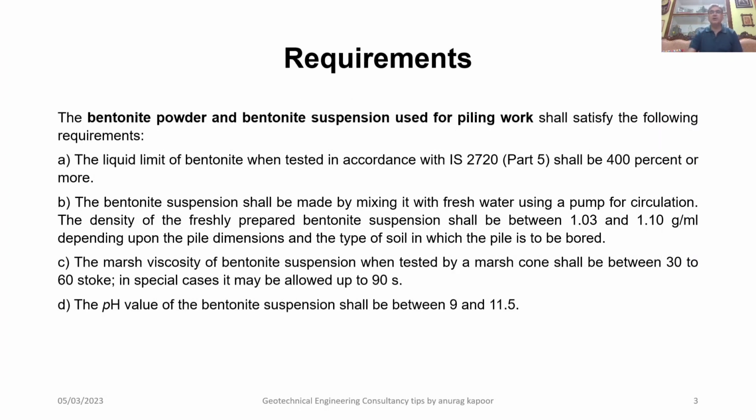Now, coming on to my last slide. The requirements of bentonite. The bentonite powder and bentonite suspension used for piling work shall satisfy the following requirements as per the two respective Indian standard codes, which I had referred to in my first slide. The liquid limit of the bentonite when tested in accordance with IS 2720 part 5 shall be 400% or more. The bentonite suspension shall be made by mixing it with fresh water using a pump for